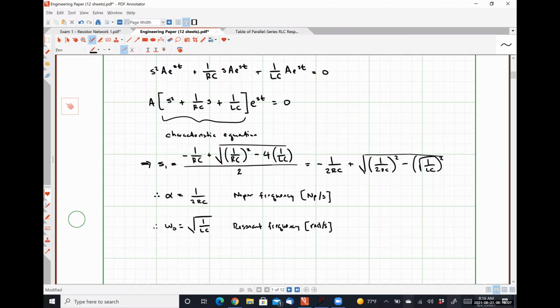If we were looking at the impedance of an RLC network, the resonant frequency is the one where the impedance becomes purely real. If we were looking at a filter circuit, which I know you don't know about yet but we'll talk about later, the resonant frequency is the frequency at which the filter hits its peak amplitude.